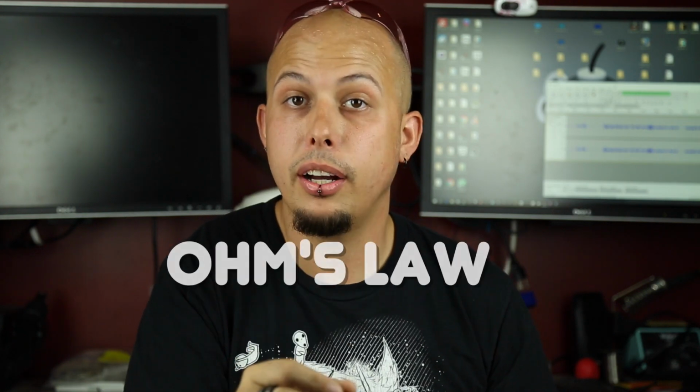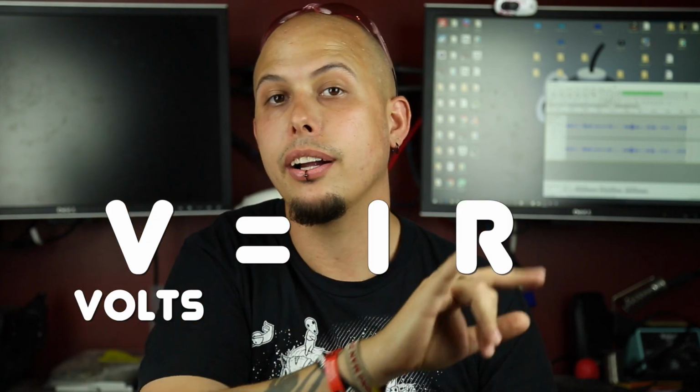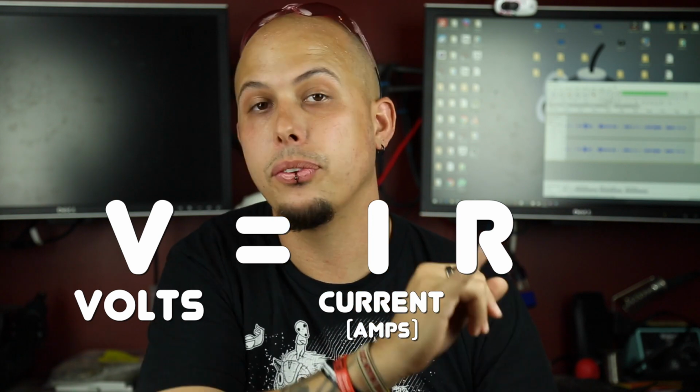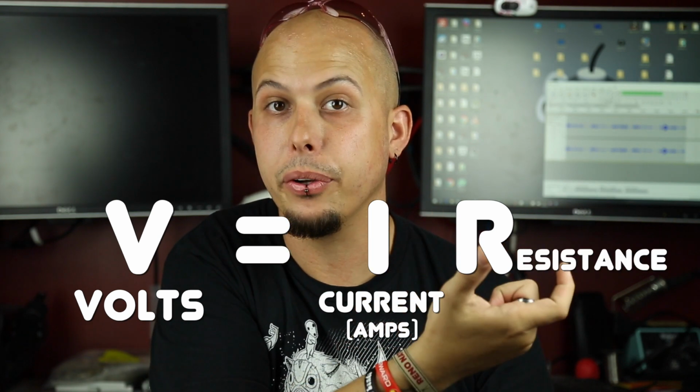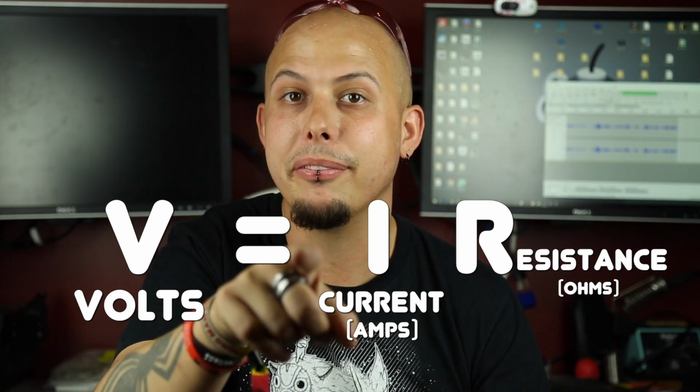One of the things that we need to be aware of when choosing resistors for a circuit is this thing called Ohm's law. And it's going to be repeated through many of our choices as we dive deeper and deeper down this rabbit hole. Ohm's law states that V, which is volts, equals IR. I is our current, and that is in amps. R is the resistance, or the resistor value, all right? And that one is in ohms, which we learned all about with the multimeter video.